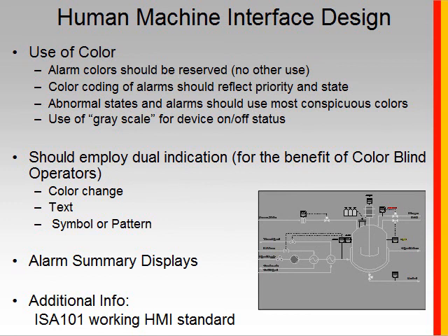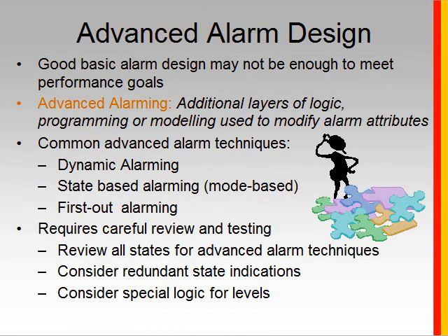One example is alarms are typically displayed on a summary display in chronological order. Human studies have found that operators can best respond to alarms if you keep the high priority alarms at the top, no matter what time they were initiated. So rather than chronologically presenting the alarms, presenting them in priority order helps improve their response. So information like that is in the standard.